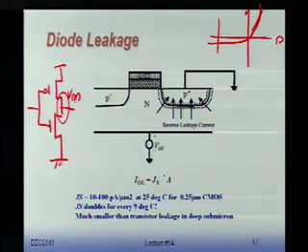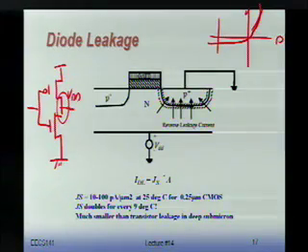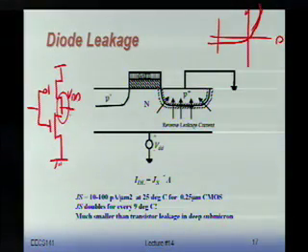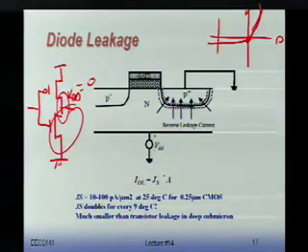So let's suppose this is an NMOS device. For an NMOS device, you look at, in this case, this is at VDD. Now this is for the ground factor. In this case, the PMOS won't leak very much, but the NMOS will leak. If this is at 0, the PMOS will basically leak, and the NMOS won't leak very much. Because it's at 0, it's at this particular point here. You don't have that much leakage.